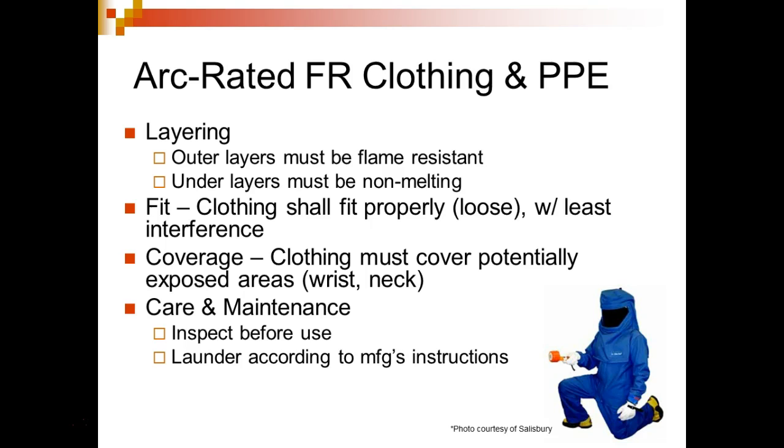Coverage. Clothing must cover potentially exposed areas, your wrist and your neck. Care and maintenance. Inspect before use. Launder according to manufacturer's instructions. Especially when you've got flame retardant clothes. A lot of times they get their flame retardancy from a coating that they put on there. And you take those things and you put them in all this Clorox and stuff, right?